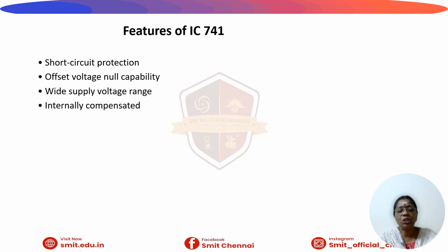And in addition to this, we have offset voltage null capability, which means it has dedicated offset null pins, pin number 1 and 5, that allow for manual adjustment to eliminate the input offset voltage and balance the inputs.